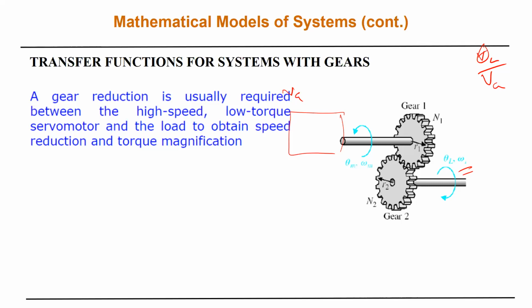The power is the same, and the power is the voltage times the current. If I increase the voltage, I reduce the current, and the current is responsible for the heat dissipation, the losses in the line. So if I want to transmit over long distances, usually I will step the voltage up. And when I reach where I want to use it, I have to step it down. So I will use the transformer.